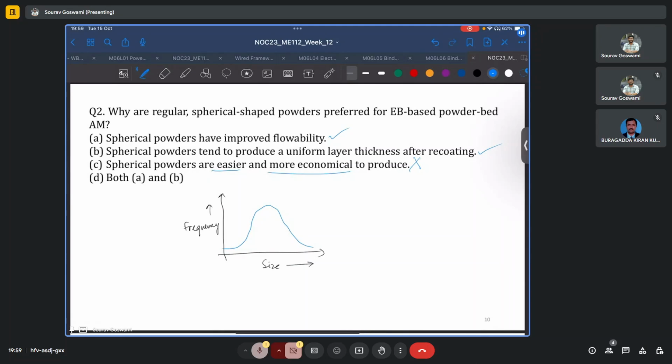And we also discussed how having a distribution of particles rather than particles of only one size is useful, because say if you have large particles, then some intermediate particles, then some small particles, overall you may end up with a better packing efficiency compared to particles spread across a very narrow distribution.